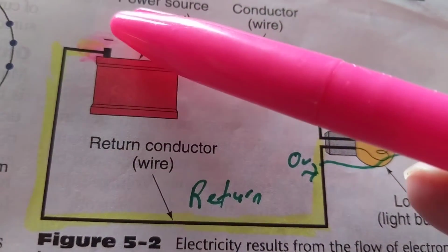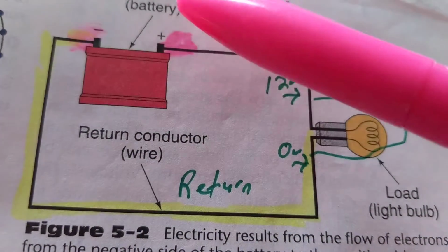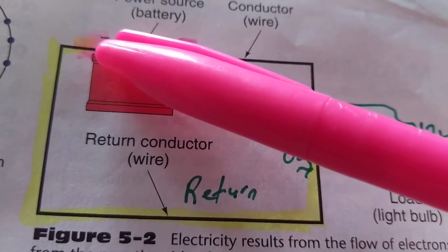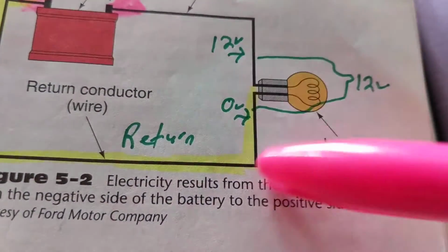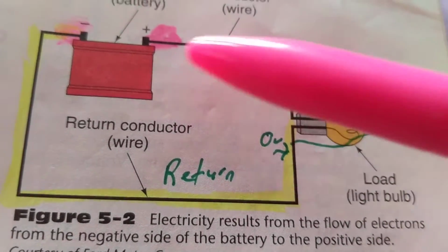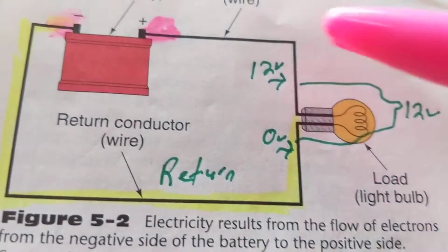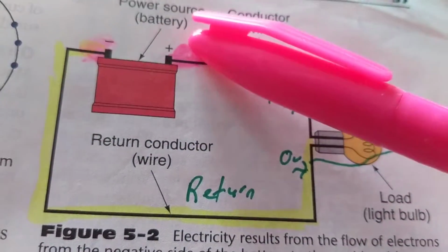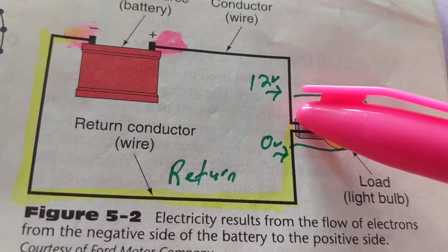How about if you have corrosion on the negative? And that's exactly the same thing, high resistance. High resistance now will give you a voltage drop, an unwanted voltage drop or a voltage loss. Remember, voltage drop means I drop voltage across the load because I want to. That's what I need. Voltage loss means I'm losing voltage across something that I don't want to lose voltage. There's a difference. We have a voltage loss, let's say, of 3 volts, just like we had over here. How much will be over here then?